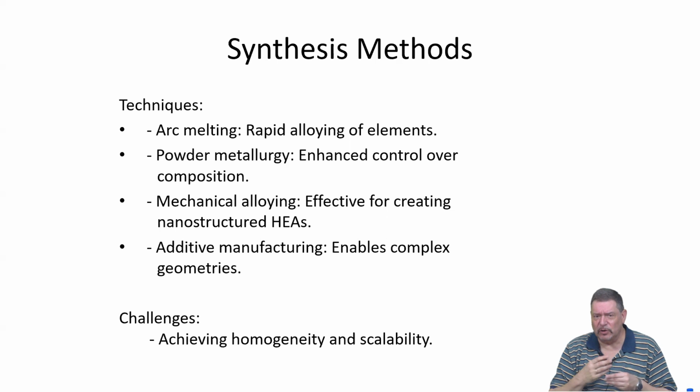That means you affect material in a different way because you make the vacancy migration enthalpy higher, so you limit diffusion while you process, you store a lot more defects, and this is a very efficient way to make ultra-fine-grained materials. And in these materials it has been proposed and verified by our work that their grain boundary structure is severely changed.